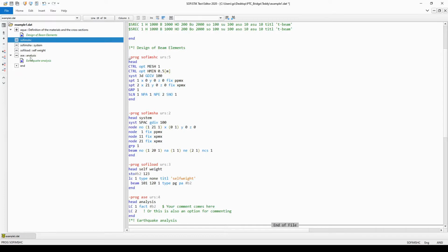Or the other way, you select the very last module and you choose, please select all of them up to the cursor position. And after having selected all the modules that you wanted, you simply perform the analysis by clicking Ctrl F12.